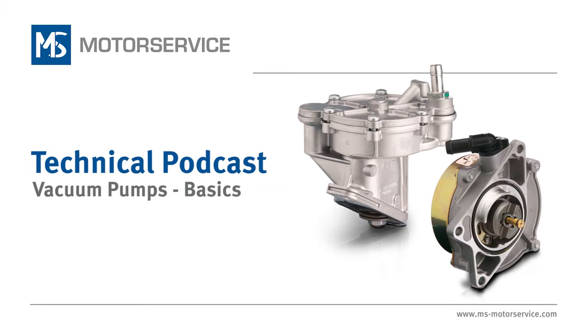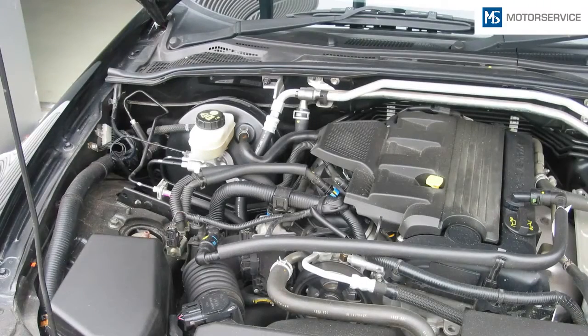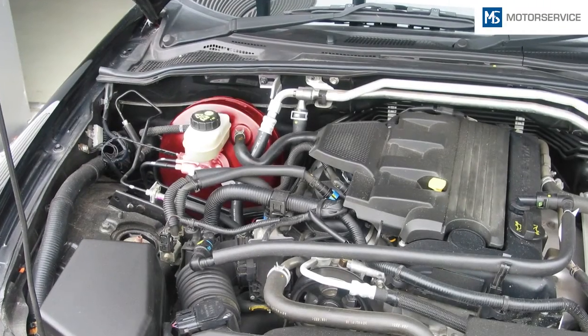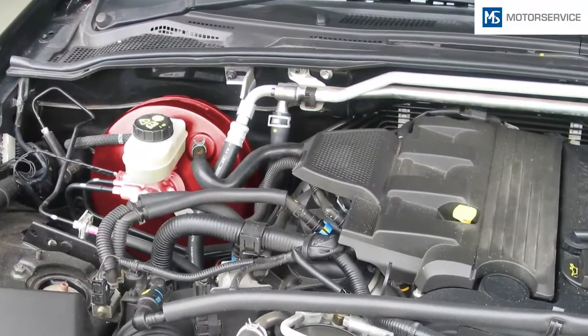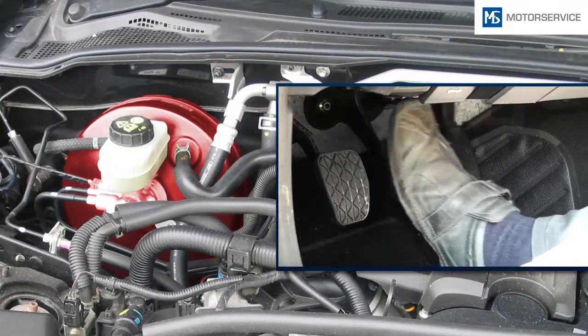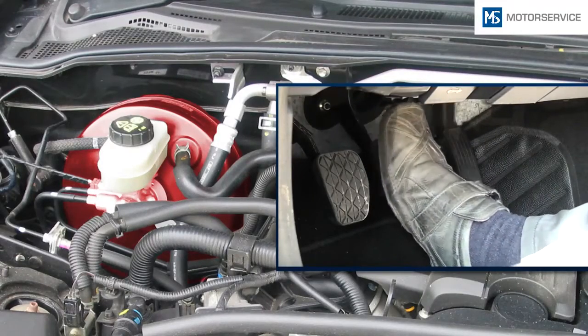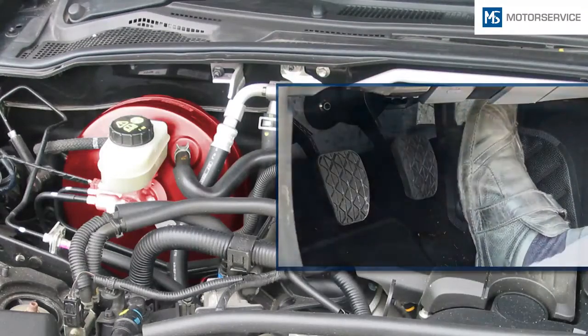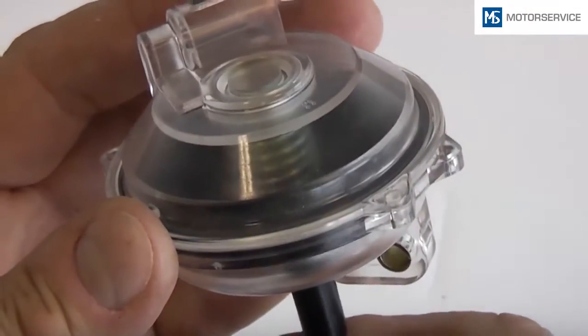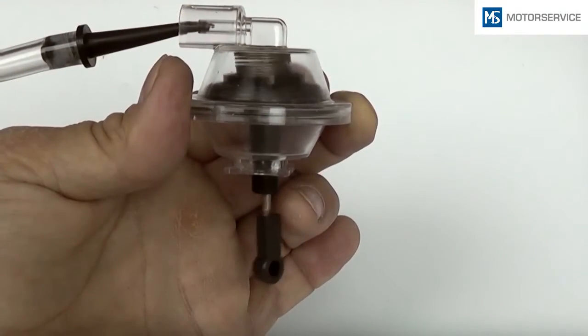This video provides you with some basics and background information on vacuum pumps. In many vehicles, vacuum is used for braking assistance and for operating pneumatic equipment. In the brake booster, for example, this increases the force applied by the foot on the brake pedal many times over. Vacuum advance units are used for positioning flaps, valves and other components.